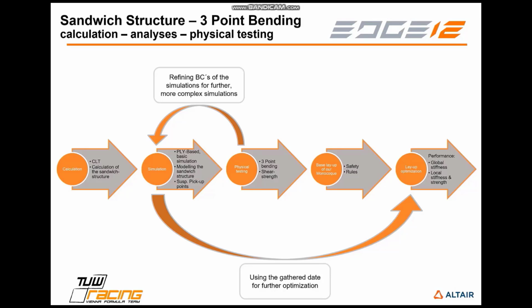But we also use the data from physical testing to refine the boundary condition, and also for more complex simulations where we model the sandwich structure itself and also the suspension pickup points, the inserts, and the splice adhesive.